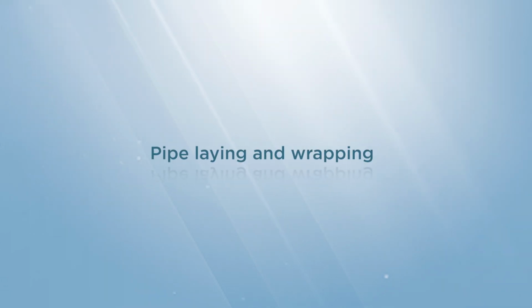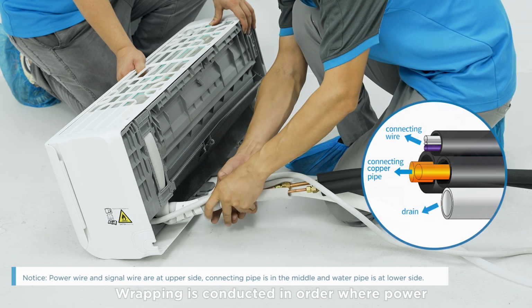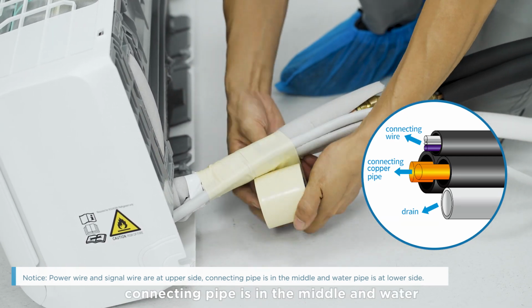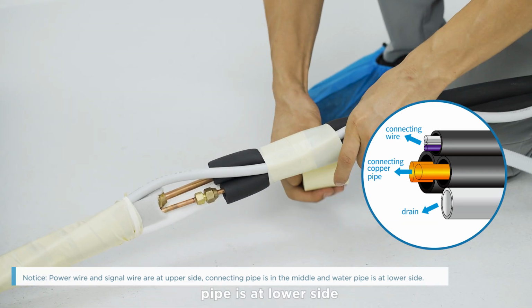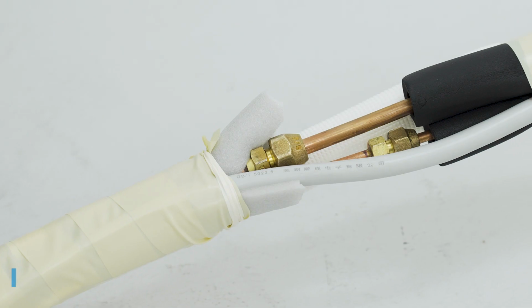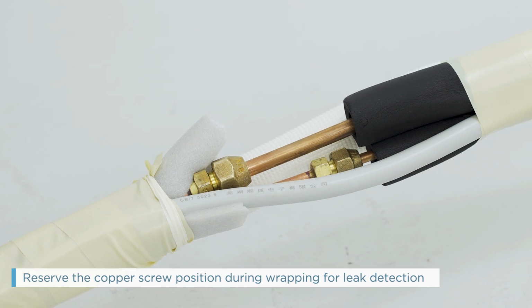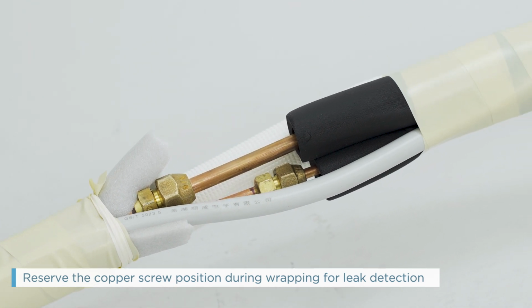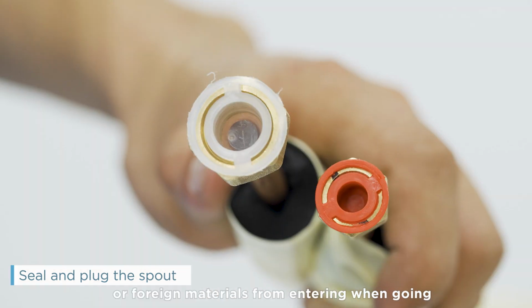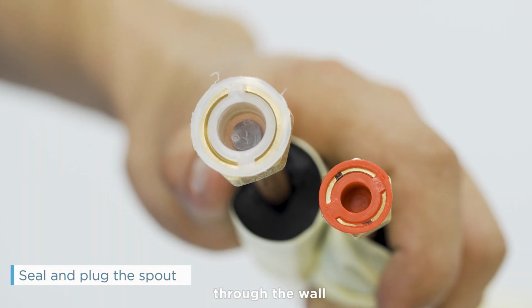Pipe laying and wrapping. Wrapping is conducted in order where power wire and signal wire are at the upper side, connecting pipe is in the middle, and water pipe is at the lower side. Reserve the copper screw position during wrapping for leak detection. Copper pipe should be sealed to prevent dust or foreign materials from entering when going through the wall.